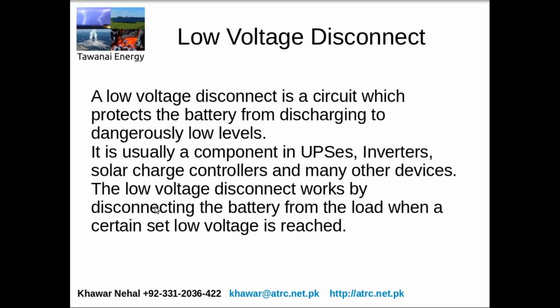Similarly, if you're using a battery, after it is completely drained, it can reach a state where, for some rechargeable batteries, it's not good for them to be completely discharged. For example, a lead acid battery, which is common in cars and many other areas and is one of the most common batteries: if you discharge it completely, you actually sort of destroy the battery and it cannot be recharged again, or it's very hard to recharge it. And even if you do recharge it after discharging it completely, the performance of the battery will be almost negligible, like you wasted the battery.